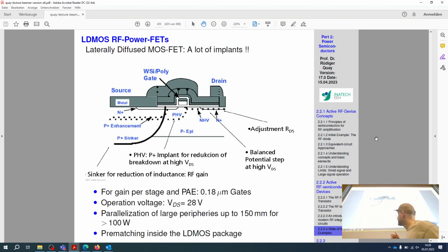Now, simply moving to a technology like silicon technology is not possible. It's the traditional silicon node. Why? Because such nodes are mostly applicable for low power and for computing applications, such as fast switches to shift bits. We don't want to do that. We'd rather want to have high frequency capable devices that have a large gate width such that we can produce a lot of output power.